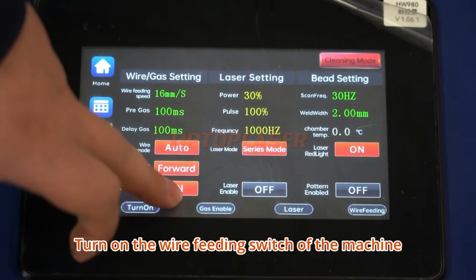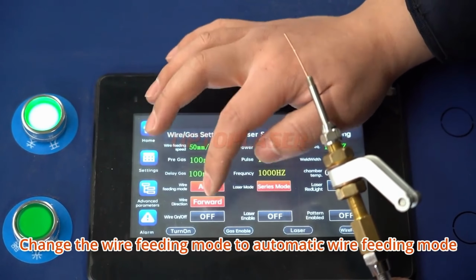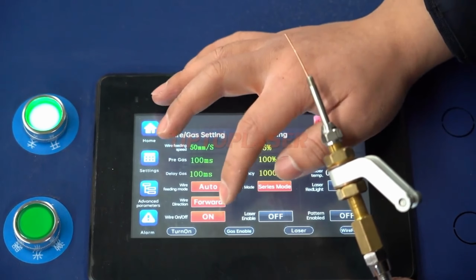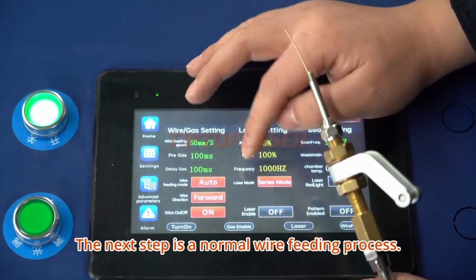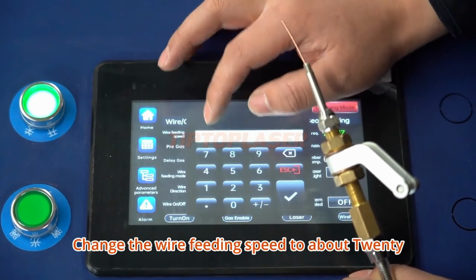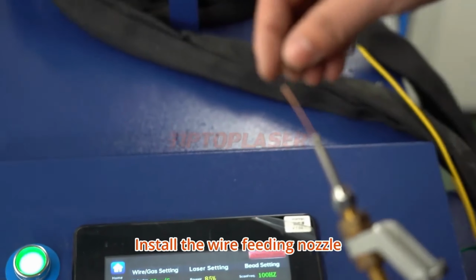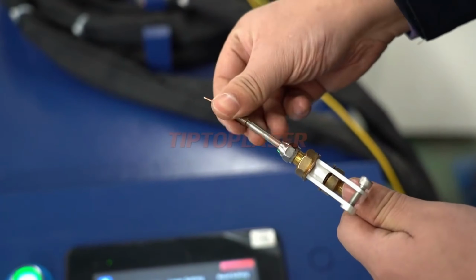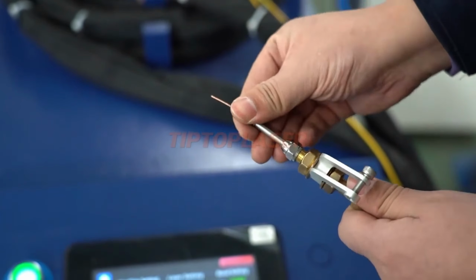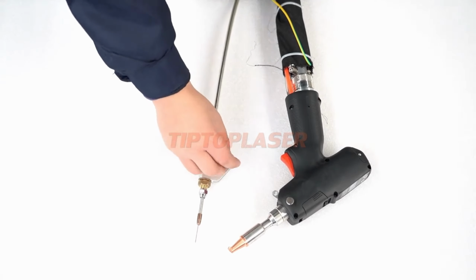After completing the wire feeding process, change the wire feeding mode to automatic wire feeding mode. Wire feeding direction is forward. Then you can do it when welding. The next step is a normal wire feeding process. Change the wire feeding speed to about 20. Adjust to a normal range. Install the wire feeding nozzle. Okay, this completes the installation of the wire feeding hose.